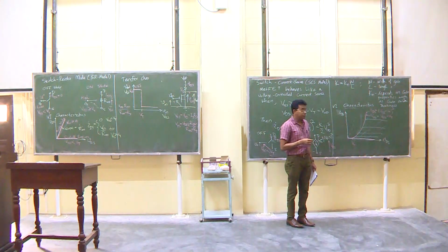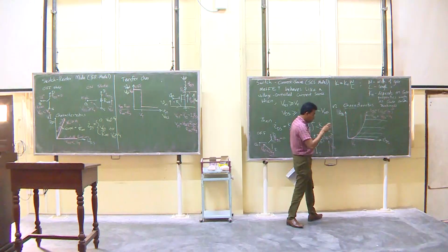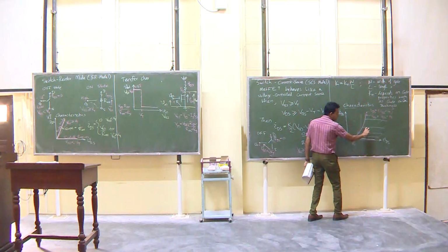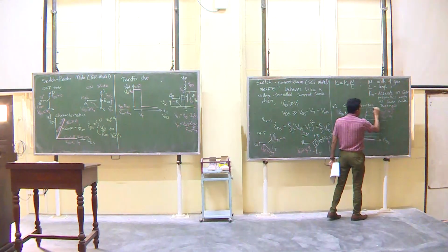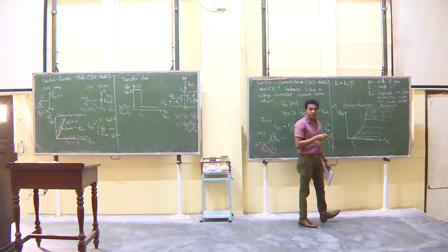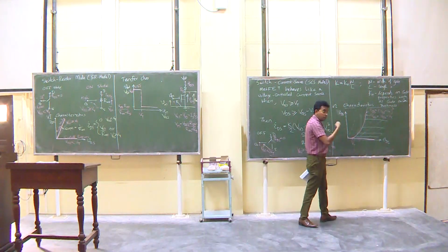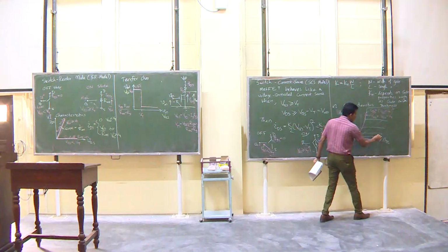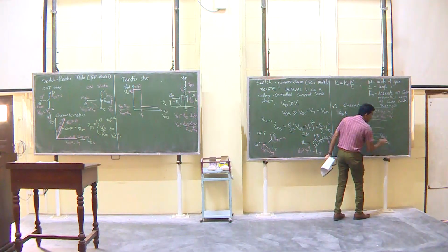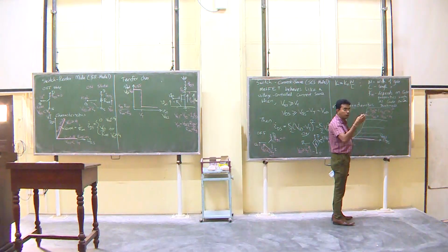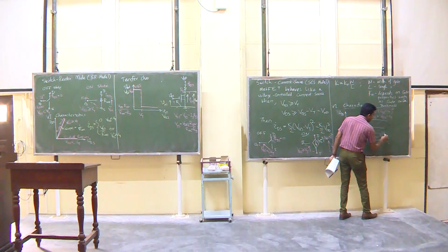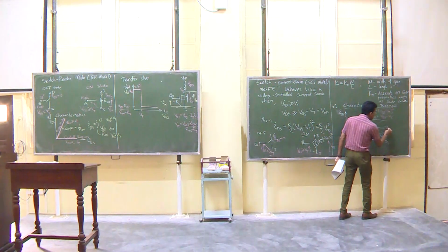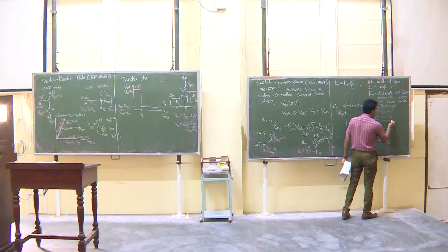Likewise, you will have different lines. Please note that I have not kept these distances equal. They are actually increasing, because it's a quadratic relationship. So if this is VGS1, let's say 1 unit above the VT, 2 units above the VT, and likewise VGS2, VGS3, VGS4,